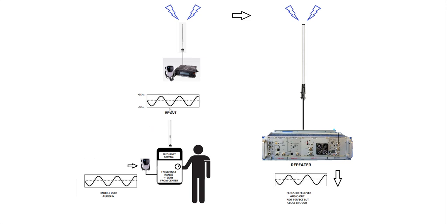But the big thing to understand is that we are not putting this signal on this carrier. We're simply mimicking the signal by moving the carrier up and down in frequency, but the signal itself is not here. That's going to be real important to understand. It's a big concept when we get to our next phase, which is the receiver.